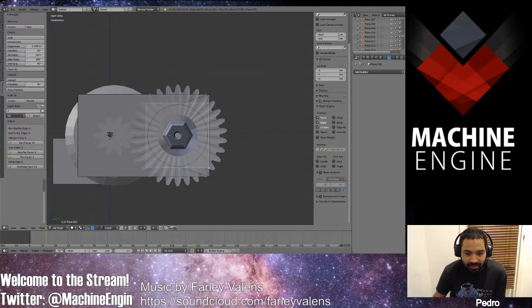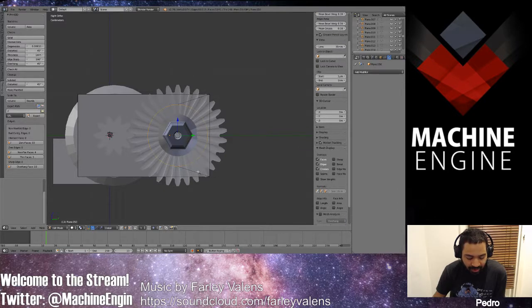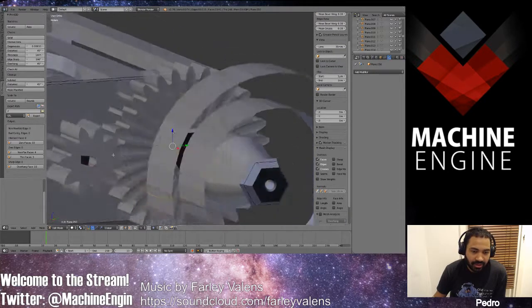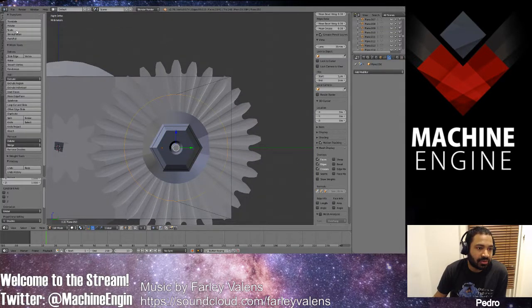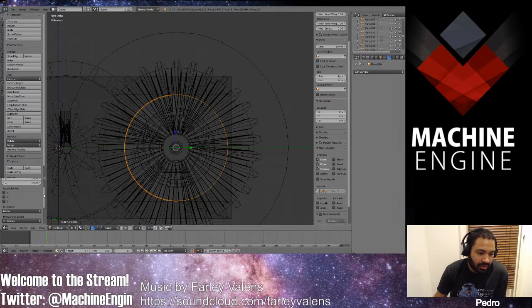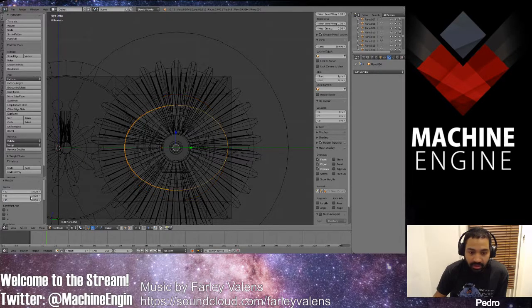But since I'm gonna be messing around with it, what I'm gonna do, did I grab them both? Yeah, cool. What I'm gonna do is reduce the size of the hole slightly. Let me put that in wireframe. That's Z. Put it like that. Whoa, 0.8 is a lot. Oh no, not that. Put 0.9. Yeah, 0.9. And Y, Z and Y.